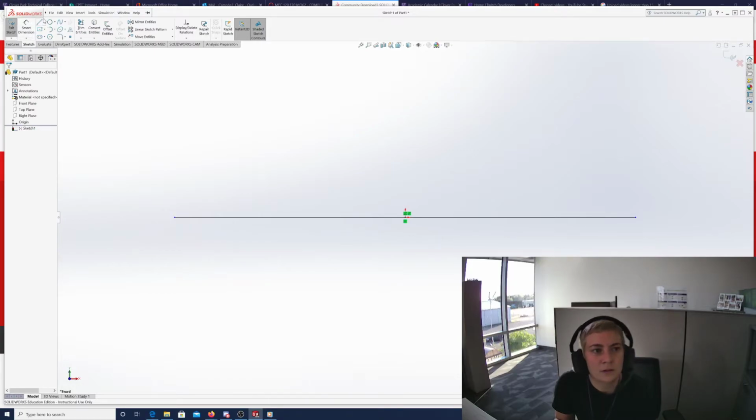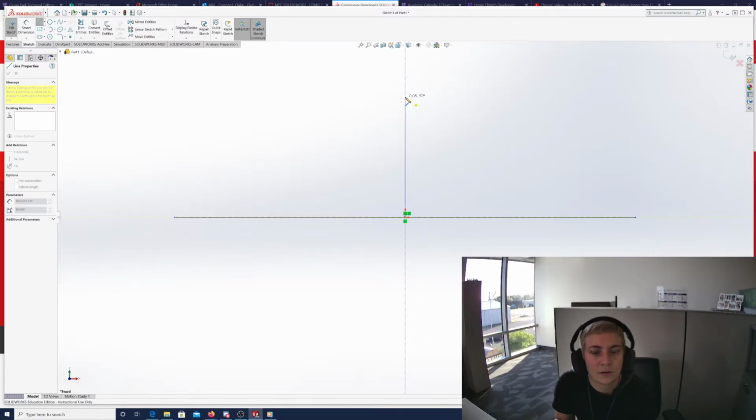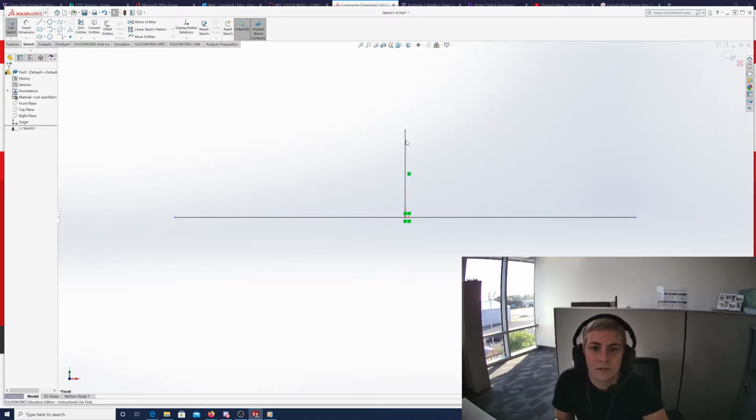The next tool in our little toolkit here is a circle. I guess I should show you too, you can just do a basic line that you start at the end. So let's start at the origin again. Click, and that's just going to give you a line from where you started. It's not going to go in two directions. You can tell when it's vertical because it does this dotted line thing. You can tell when it's horizontal because it does a similar dotted line. You can also do any kind of diagonal you want, but let's just do a vertical line here. All right, and then hit my escape key.